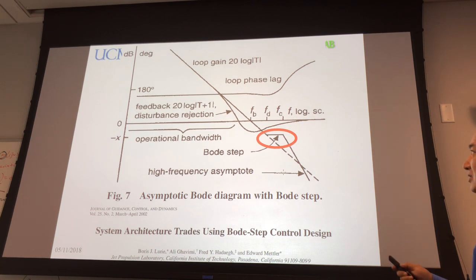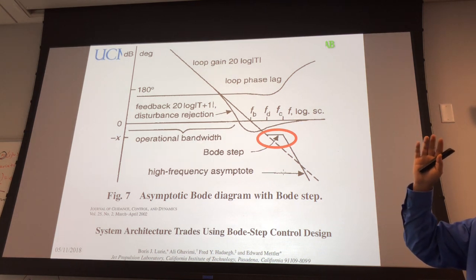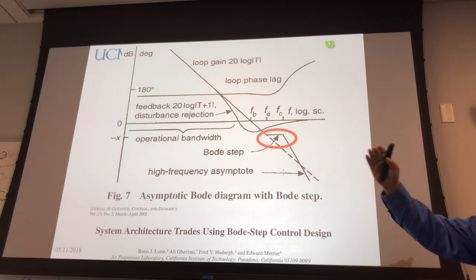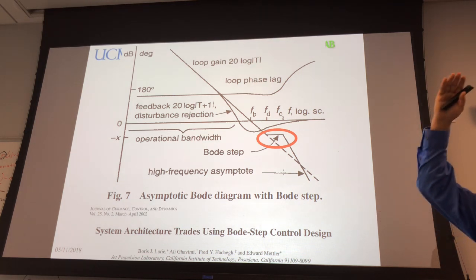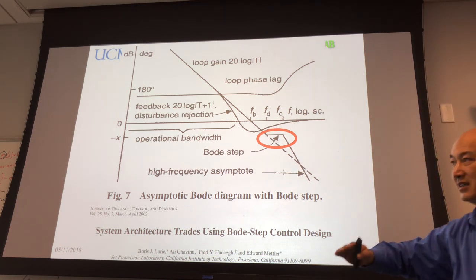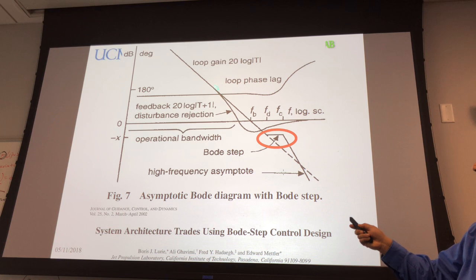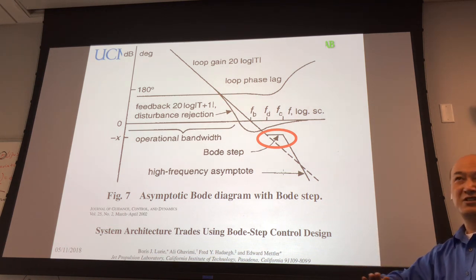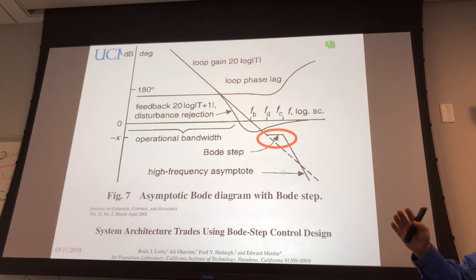Okay, so if you have a motion system, what's the open loop? It is minus 40 dB per decade. It's a double integrator. You have two integrators. He said that you should go double integrator, but then you should cross over with, I remember, 1.6 order.